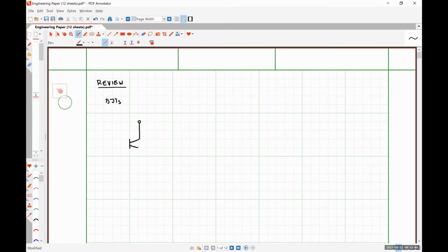Since it's been a hot minute since we've looked at a BJT circuit, we implement a current source, specifically an NPN current source, by applying a fixed bias voltage to the base terminal of our NPN transistor and grounding our emitter terminal.